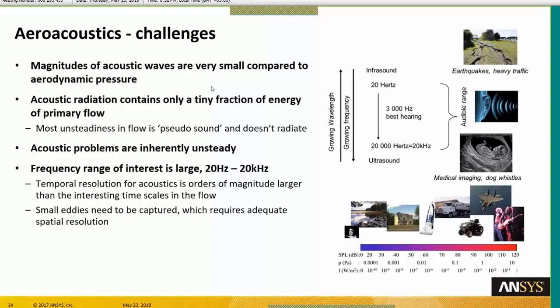Another problem is that when you are talking about aeroacoustics, you are typically talking about unsteady phenomena because you are propagating an acoustic wave. So it's clearly an unsteady phenomenon. It's difficult to represent with a steady approach, nearly impossible, because the constitutive equation for acoustic wave propagation is clearly an unsteady equation with a temporal term, which is quite important. The frequency range of interest, remember when I was talking about the human ear, is 20 to 20 kilohertz. So that makes quite a large range with different orders of magnitude, and usually it's better to use a decibel scale which is based on logarithmic considerations.